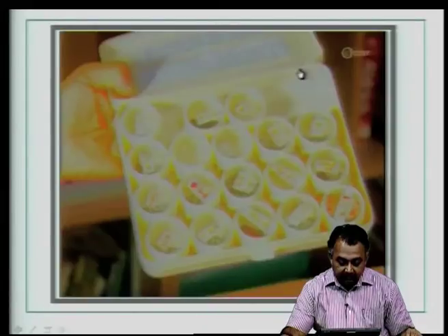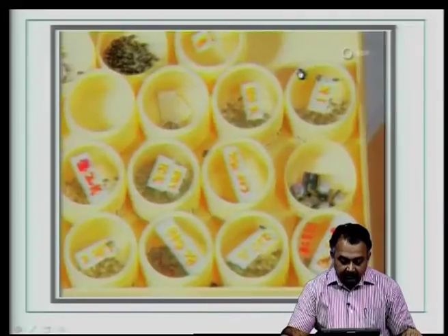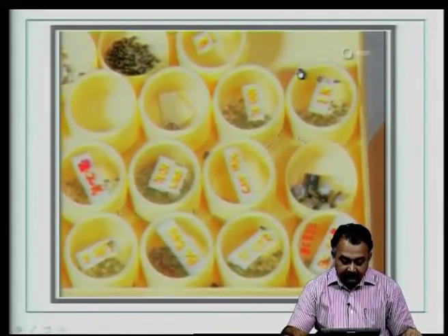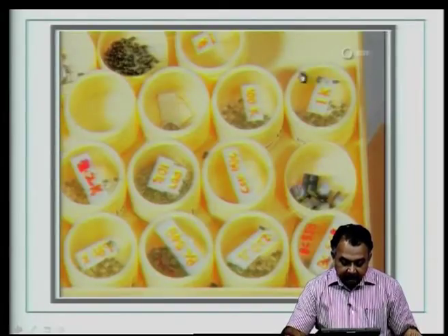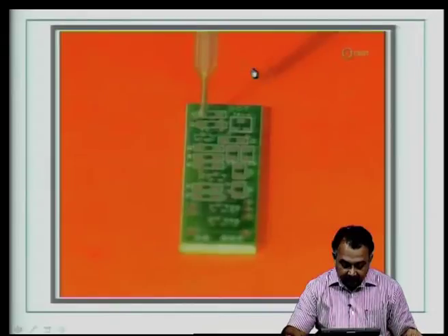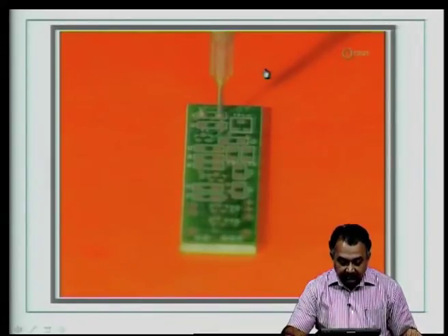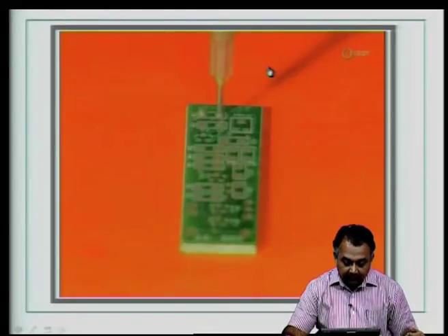That will help in good mass distribution over the entire board. Now, the components for the prototyping have to be ready. You can see here in this particular slide, there are a few, all of them are surface mount devices, of various sizes and formats including resistors, potentiometers and so on. And this is the board, and you can see here the technician is now dispensing based on the experience of dispensing quite a few boards.